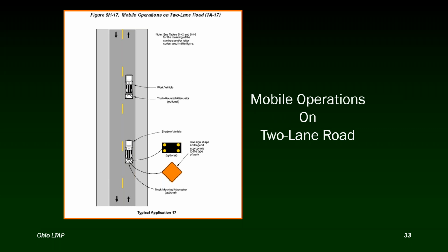So specifically the four corners mode, not the straight line for caution. That's because there were too many crashes or near misses with the straight line, and because the drivers would mistake that, they actually would think that the bulbs in the head of the arrow were burnt out, and so that confused the motorists, and they went around the shadow vehicle anyway, thinking that it was not meant for that purpose. So there was oncoming traffic, and that would either cause a crash or a near miss. And so that's not good. So if you use the four corners mode, that eliminates that mistake.